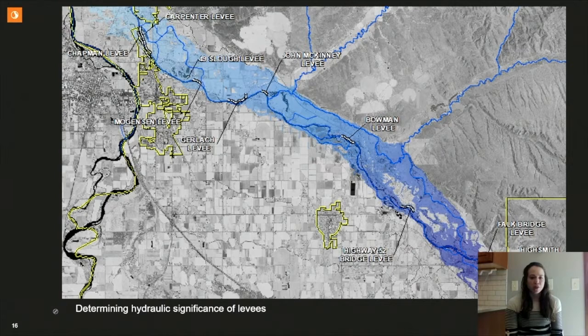To create the regulatory data for this model, first we need to determine which natural valley scenarios needed to be included. The scenarios are included if the levee is determined to be hydraulically significant. The FEMA guidance describes 3 scenarios which indicate if the levee reach is not hydraulically significant. The first scenario is that the levee is fully submerged and the landward conveyance is in the direction of river flow. This didn't really apply to any of the levee systems in this modeled reach.